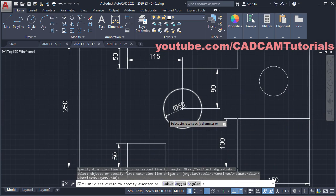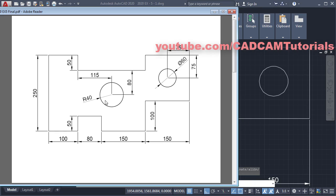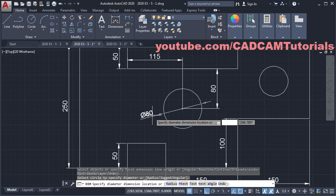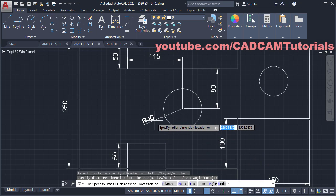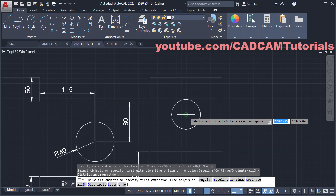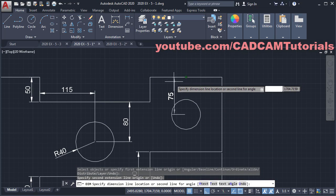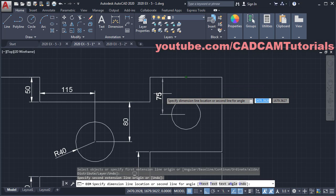Then click on this circle. Now here this is diameter. To convert this diameter into radius, click on radius and click. Then click on this center point. Click on this midpoint. Take your cursor on this side and click.